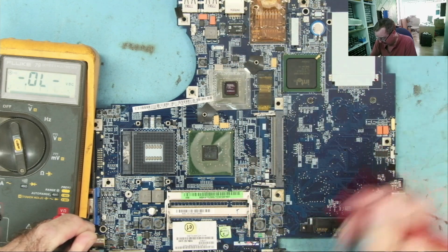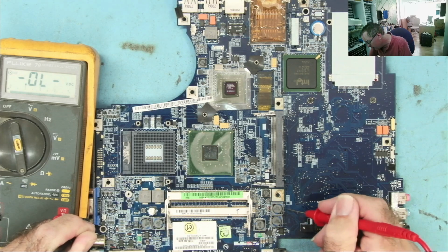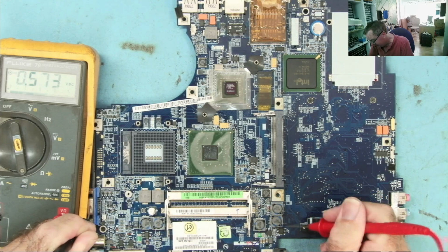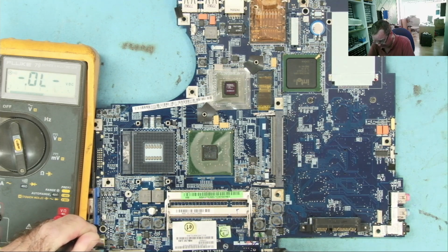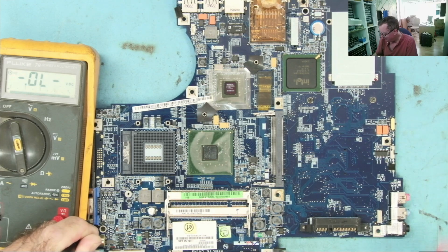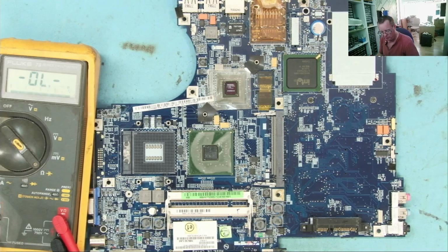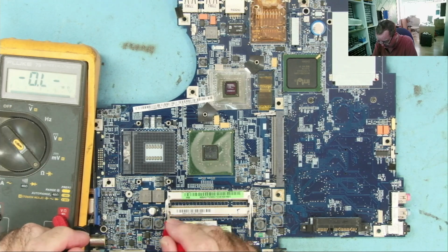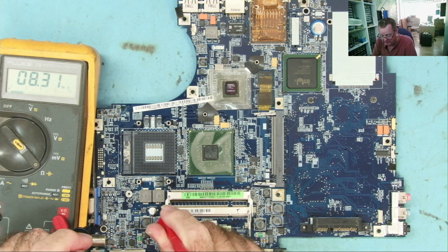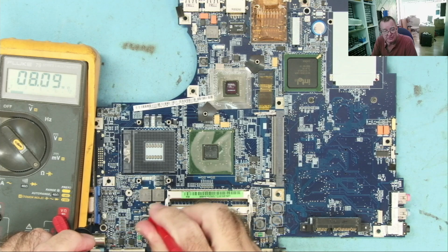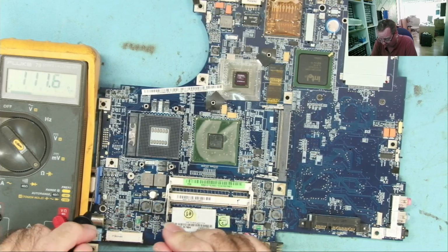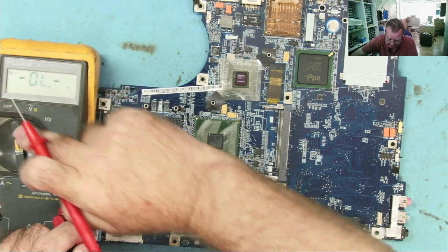Okay. We have a few more over here. That reads like a diode junction. That reads high. That reads like high, yeah. But they look like there's some shorts on here, but let's have a look. Let's go to ohms range and take the same measurement. So this one is high, 8.2 mega ohms. The same. This is the one that read quite low. It's 160 ohms.